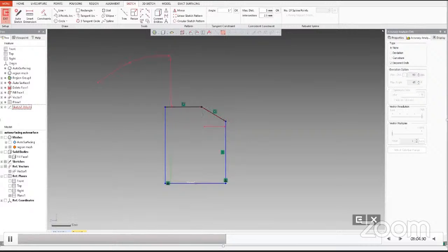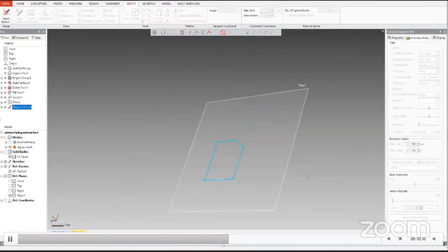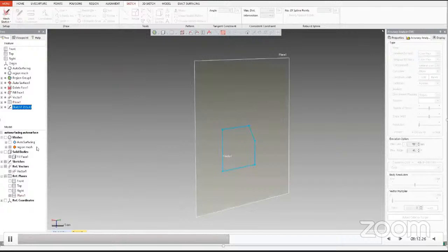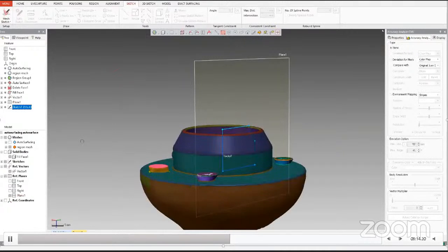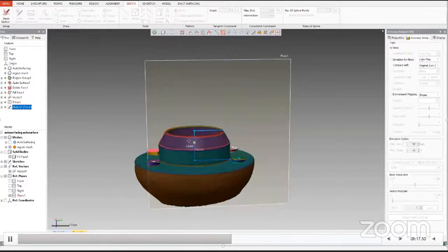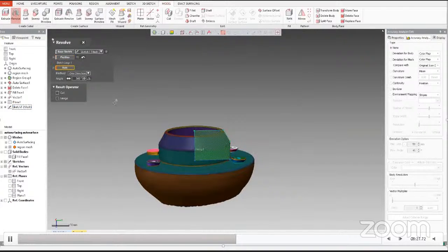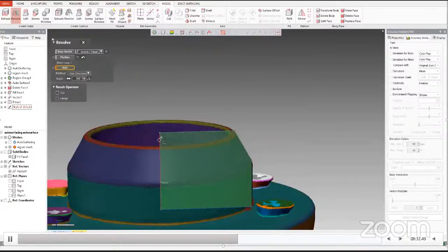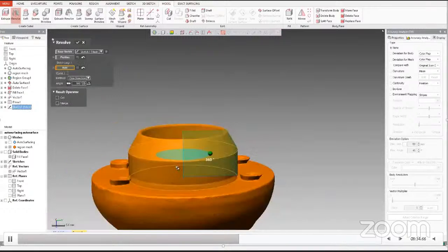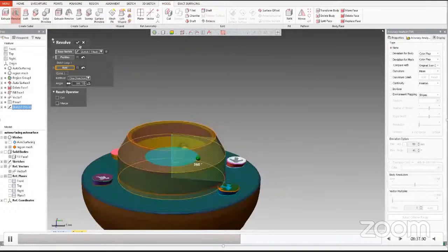Now this seems better, and the bottom of the sketch is touching the central axis of the cylinder. So we have the sketch. We can apply the revolve feature command and revolve it about vector one. So go to the model, select create solid revolve feature, and select the axis, which is this vector one, and then it will revolve the sketch 360 degrees, and we will have the solid body.